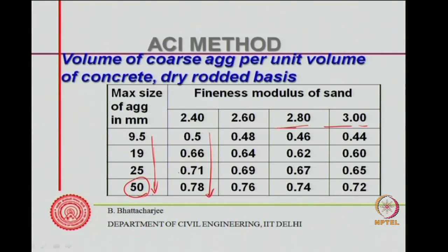So, as the MSA increases, total aggregate content increases, in other words sand content would reduce, because it will have a better packing.